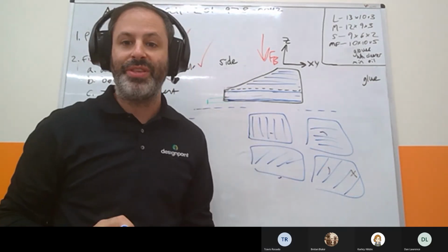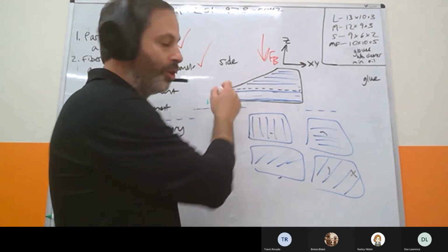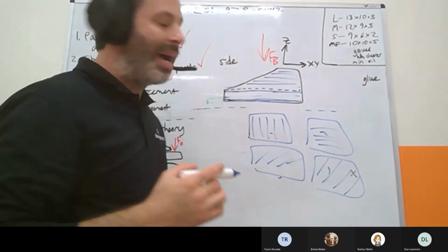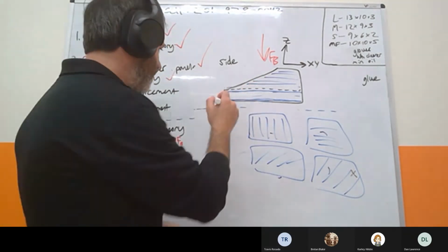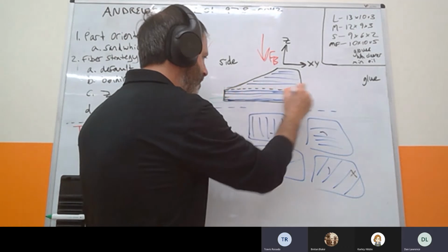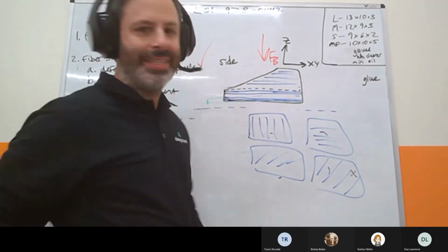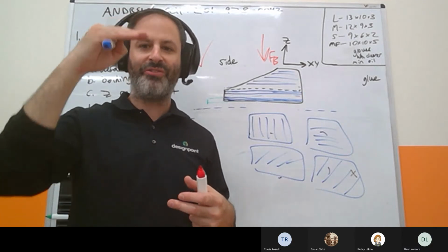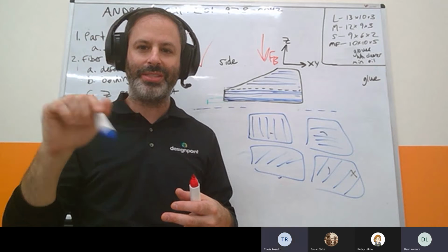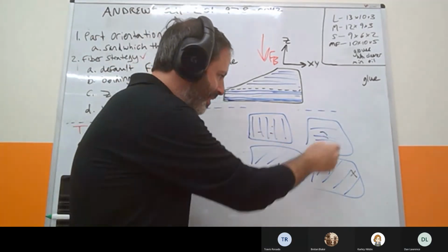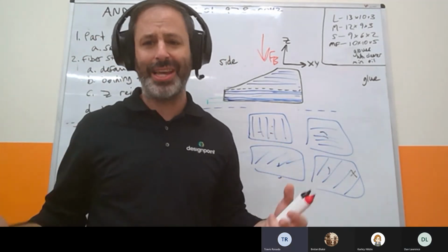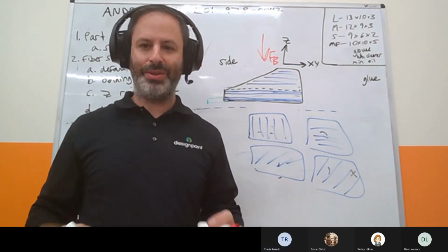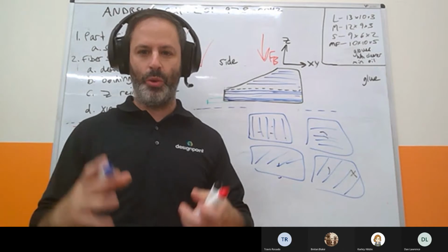Now, if this load was larger, a fairly big bending load here, I might double my sandwich panels and add a second one. But when I'm adding a second one, I'm adding a second set of 4. You want to go 4, 4, 4 because you want it to have all the layers of the cross hatching. Now, that being said, if you had 6, would it be the end of the world? Not really, but that's how you want to think of it, in sets of 4.